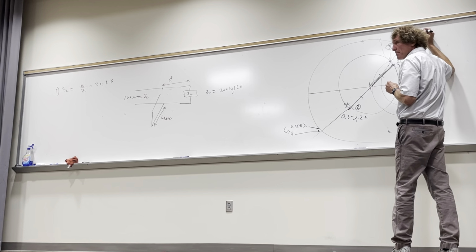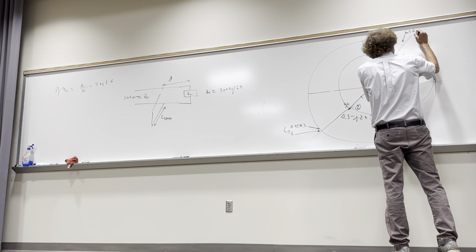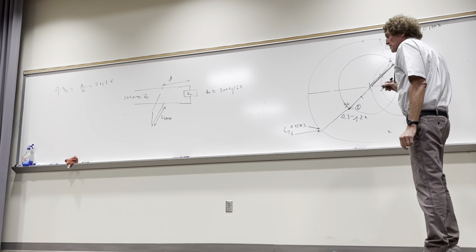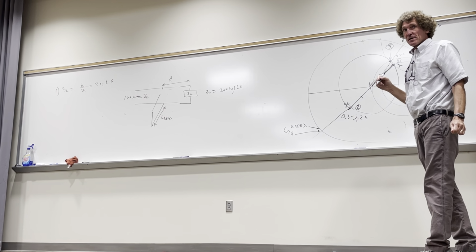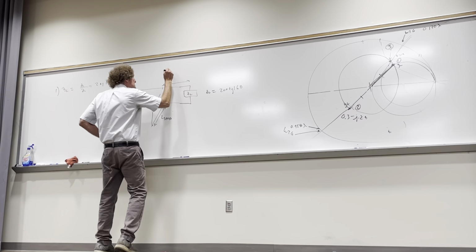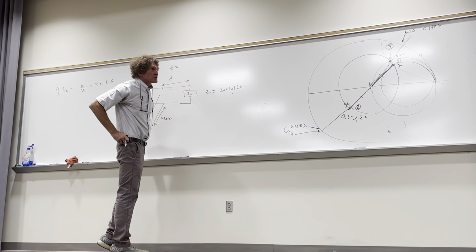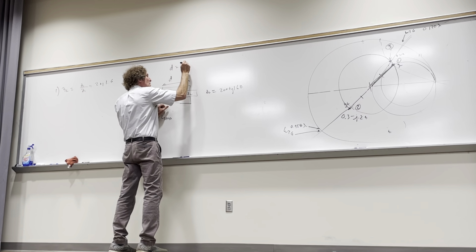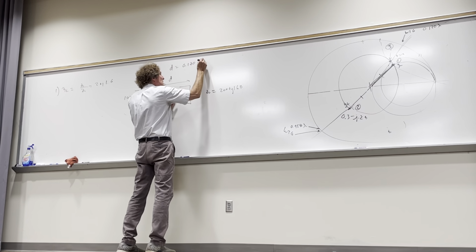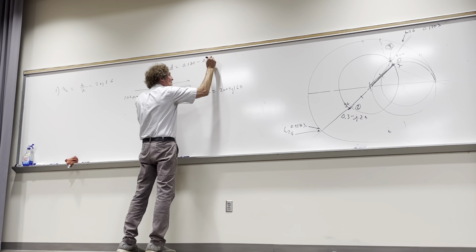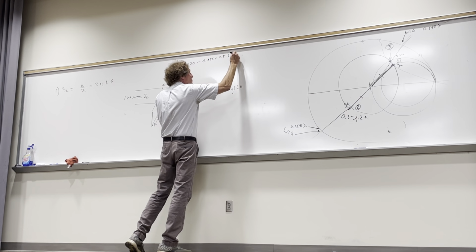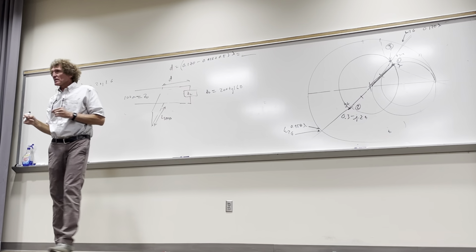And what about this value? That's where it lands over 1. Yeah, that was 0.170. And that would be wavelengths towards generator, right? Y'all with me on this one? So now when we figure out the distance D right here, this distance D would be wavelengths towards generator number 0.170 minus this number 0.458. And then we have to add a half a wavelength so it becomes positive. And what's that value? That tells us it's going to be just a little less than 0.25.